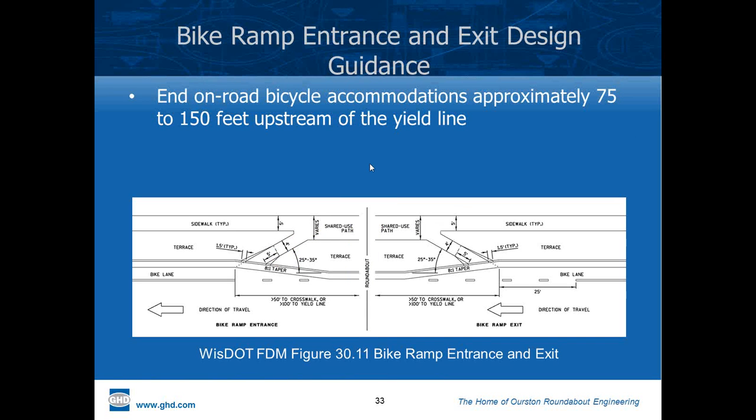Some of the design development over the years, refining the bike lane treatment with this 8-to-1 taper, fairly narrow departure, so it's not the width of a driveway or look like an access, and some sloping, the angle about 25 to 40 degrees, and joining up with a sidewalk where it's widened out to a shared path use. So this is at least an 8-foot, preferably 10 feet shared path connecting up with an existing sidewalk.